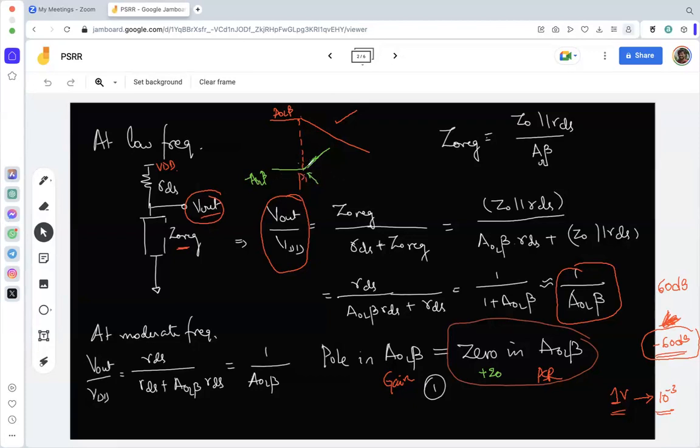Now the rejection slowly worsens, meaning the curve is moving up, meaning any noise at the VDD starts to appear slowly with a higher quantity at the node Vout. The gain is slowly increasing. But till where? There should be a limit, right?